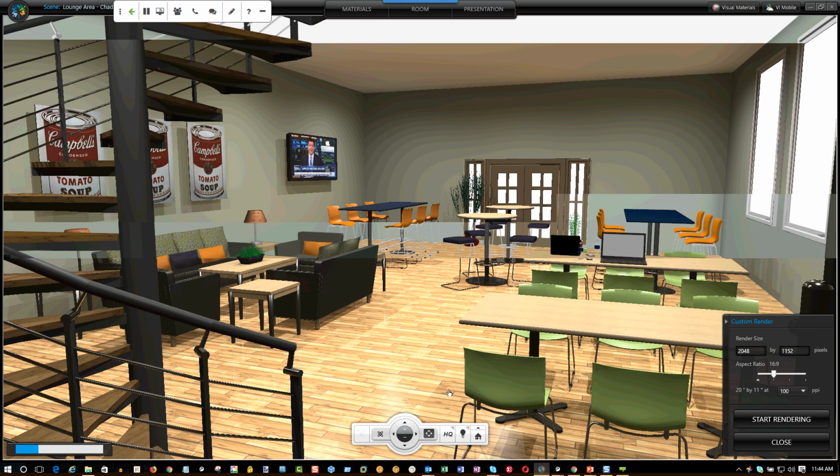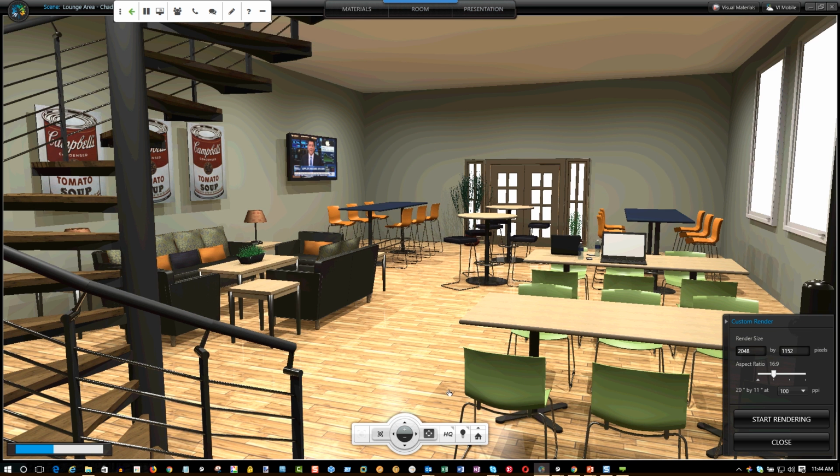And I specifically mention that because when I've been doing these custom renders in the past, if you do the first one and you set it up the way that we are here, where I do HQ and I get it just the way I want, I create the rendering, and it doesn't turn out the way that I want, a lot of times I'll go back in and do it again, and that is the thing that I forget. I forget step 0 of making sure that the render quality is the way that I want it to be. And as we go through, you're going to realize that the render quality is an important first step, because once you start the rendering, you can't stop it. It's going to go through and do its thing, and it may take minutes depending on the size of the render that you're asking for. So you're kind of committed once you hit that Start Rendering button.